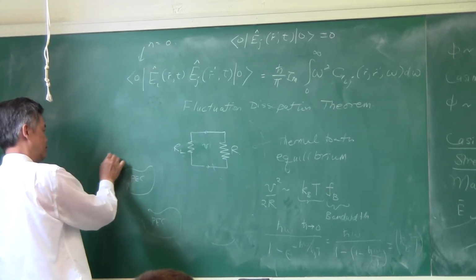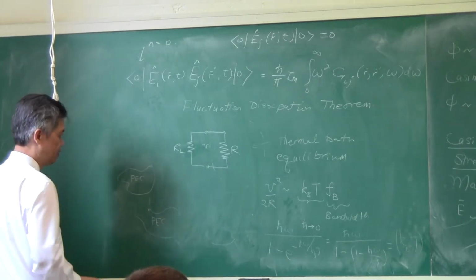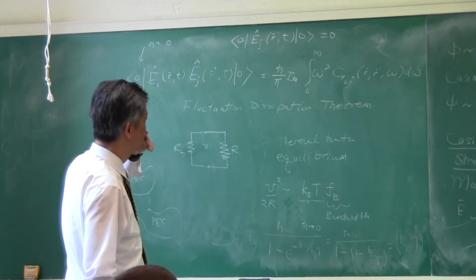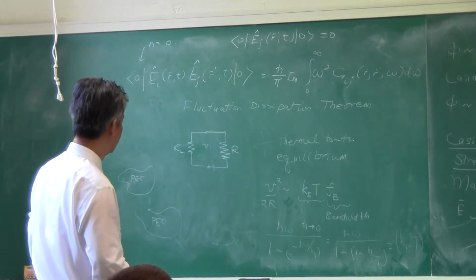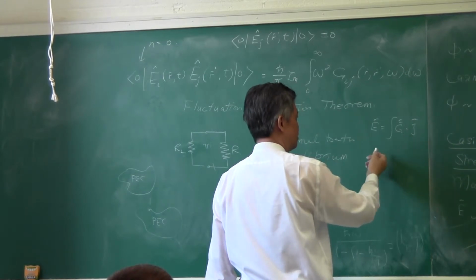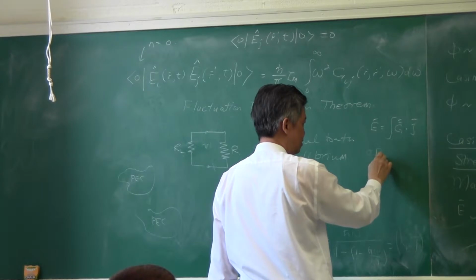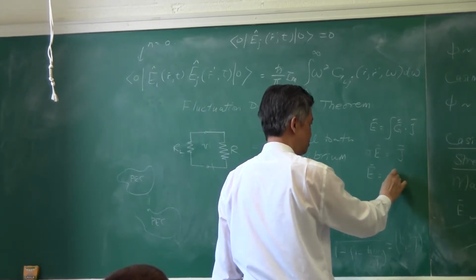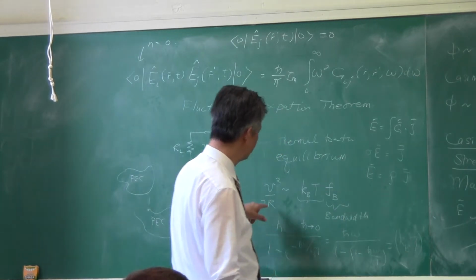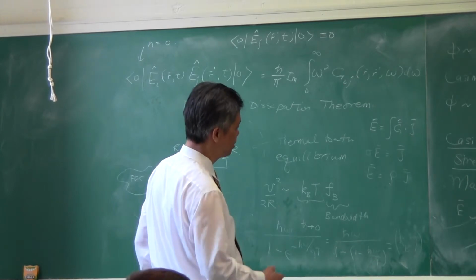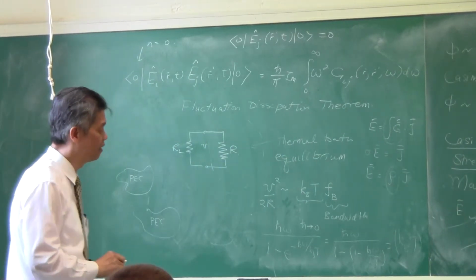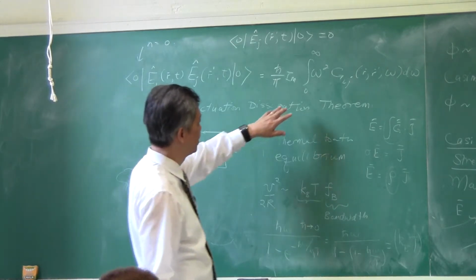and you're going to acquire some energy, or some E field around this thing, and that E field is proportional to this thing, which I will not derive, but this is essentially a relationship between E and J, G is the Green's function times J. Okay, so we know that J is equal to sigma E, E is equal to maybe rho times J. So in the resistor, rho plays the role of the resistor, but in the more complicated generalized sense, the Green's function plays the role of the resistor, especially the imaginary part of the Green's function.